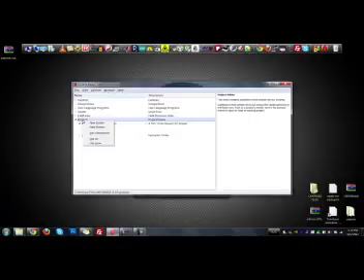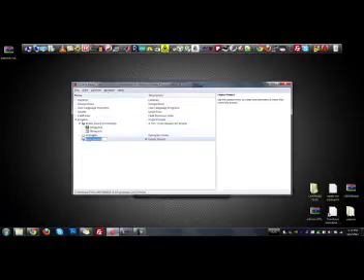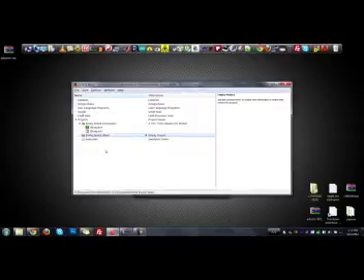Right-click on Projects and hit New Project. That'll make a new project folder. By default, in Windows, it'll be C, Program Files, Eagle, Projects, New Project. But you can add additional directories for projects if you click on Options up here and add that to your directory. But for now, we'll just put in the default location. I'm going to call it Blinky Board New, because this is the one we'll be working on. Okay, and we've created our project.